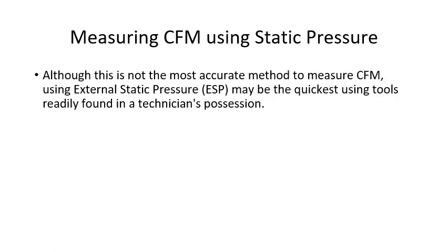Let's talk about measuring CFM using static pressure. This may not be the most accurate method of measuring our airflow using external static pressure, but it could be the quickest, and it gets us close as long as we take good readings using tools that are readily found in a technician's toolbox.